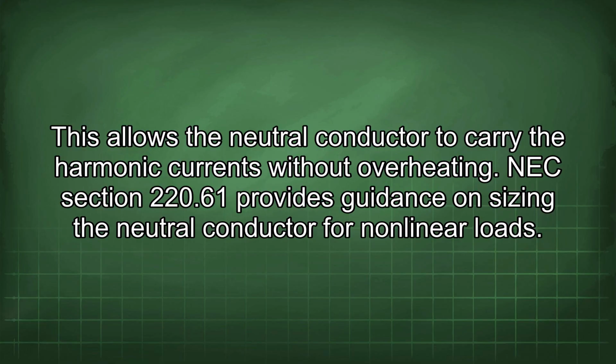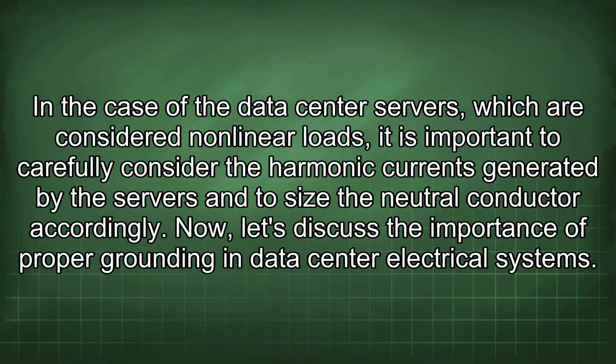NEC section 220.61 provides guidance on sizing the neutral conductor for nonlinear loads. In the case of the data center servers, which are considered nonlinear loads, it is important to carefully consider the harmonic currents generated by the servers and to size the neutral conductor accordingly. Now let's discuss the importance of proper grounding in data center electrical systems.